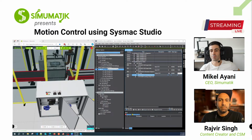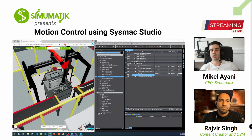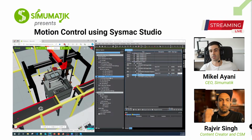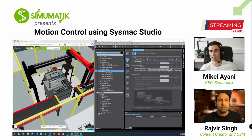Here we see that we have a motion group, and here you add the 4 axes, because as you remember from the previous webinar, this portal has 4 axes, X, Y, Z, and we can also control, which we haven't used yet, the gripper with rotation in the Z axis. So it was adding these axes and doing some simple setup, just the limits and units.